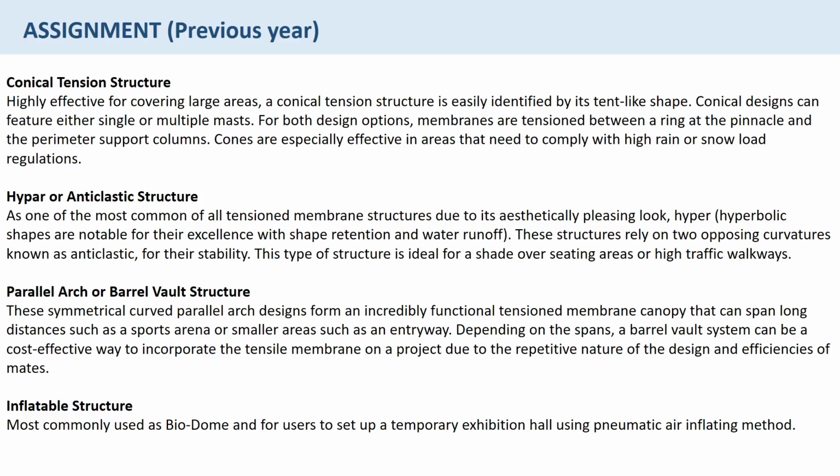High par or anticlastic structure. As one of the most common of all tension membrane structures due to its aesthetically pleasing look, hyperbolic shapes are notable for their excellence with shape retention and water runoff. These structures rely on two opposing curvatures, known as anticlastic, for their stability. This type of structure is ideal for a shade over seating areas or high traffic walkways.